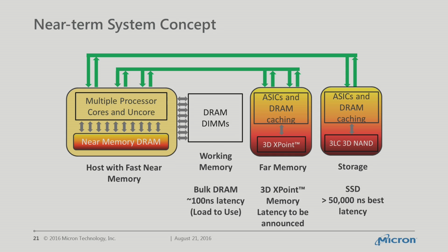Anyway, one of the Micron VPs talked about an SSD product that uses 3D crosspoint, and he cited a 10 microsecond latency for that. And I'll tell you that for that product, the vast majority of the latency is not the 3D crosspoint, right? It's all the various protocols and other things that you have to go through in order to attach the SSD to those pins that will interface with it, right? And so the part is much better than that.